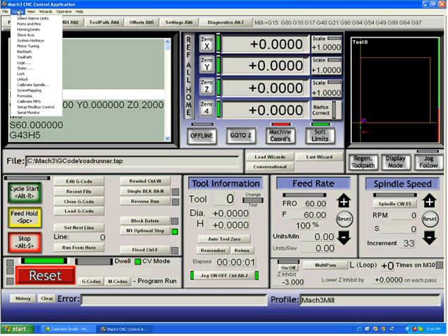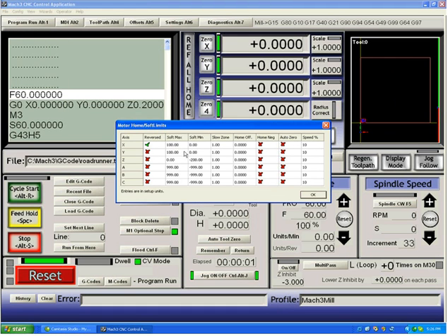That, incidentally, is programmed in the homing and limits configuration right here as my soft minimum and soft maximum. You'll see my X is programmed to 100 as its maximum, 0 as its minimum, 100 and 0 for the Y, and you'll see the Z is a little different. Its maximum is 0. Its minimum is minus 200. This is because the Z on this theoretical machine has a 200 millimeter movement starting at the top.